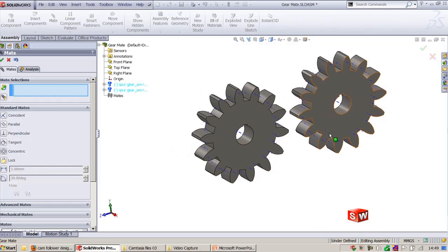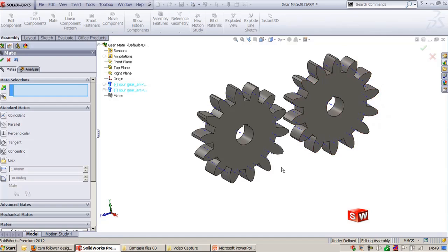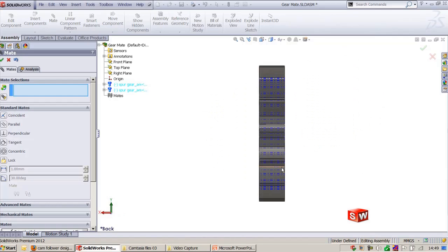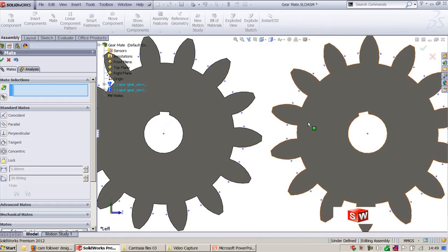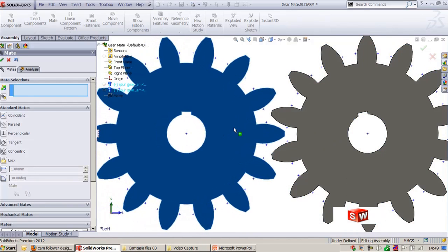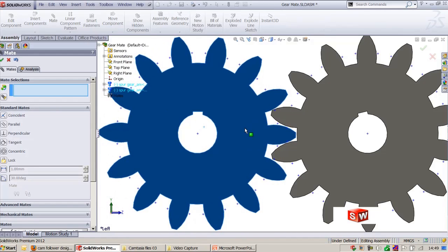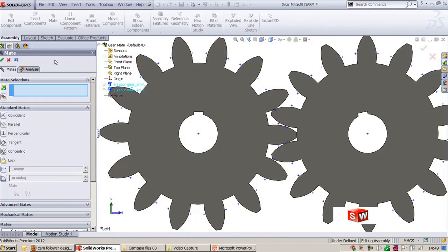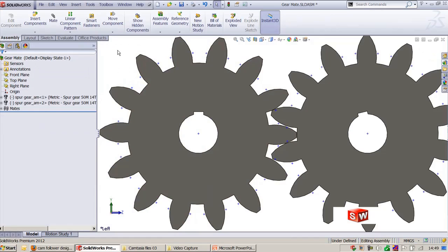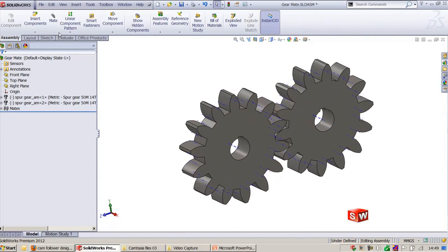Yes, and now it is able to rotate here, and now I will locate this roughly near this spur gear so that it will be easy for us to adjust. And once we place this, we'll click OK here, and now let's see how the relationship will be applied.